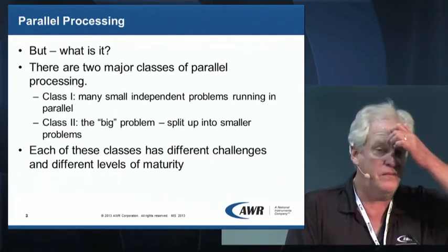But what I want to emphasize is that most circuit designers in their everyday work are actually doing class 1 when they parallel process. And these are EM projects run in parallel that are small, okay? So maybe you've got a little discontinuity, a bend, a T across, a notch T-junction, a single spiral, 2 coupled spirals.